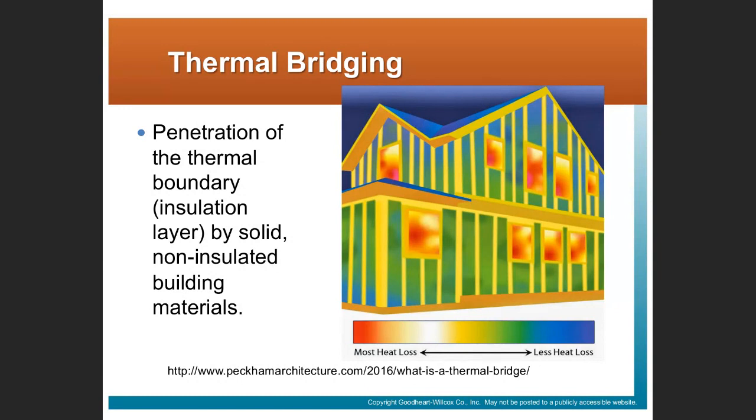And if you take one of those thermographic images of a typical wood frame house, you're going to see something like this, right? So again, if we want to make this structure more efficient, right, we've put insulation between the studs. Now we have to think about ways of reducing the heat loss or heat gain through the structural member itself. That's called thermal bridging, right? We want to look at ways of reducing thermal bridging, of making our walls more efficient.